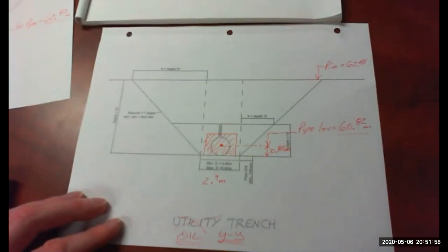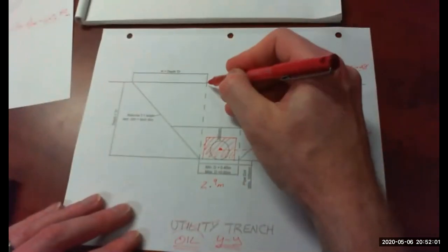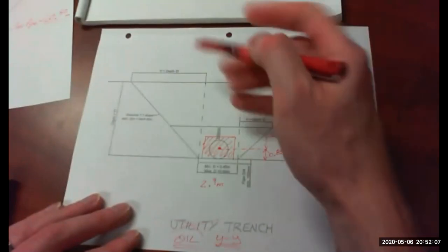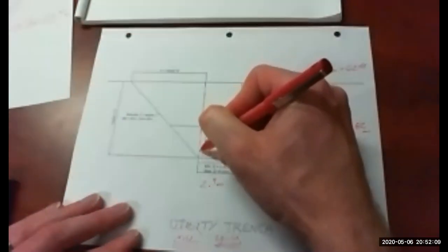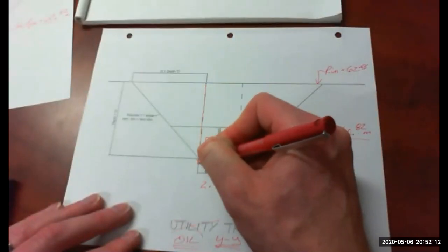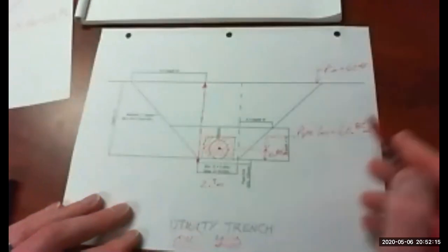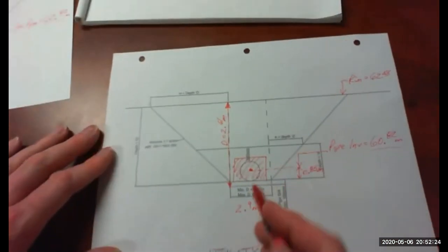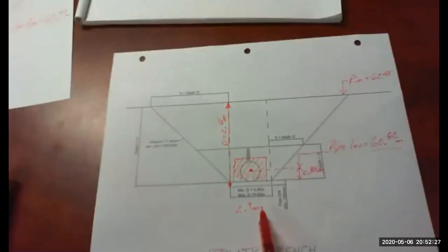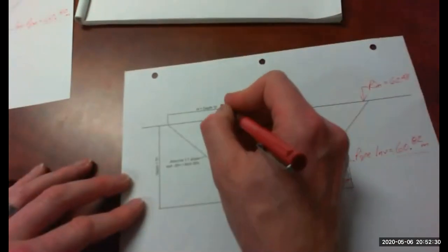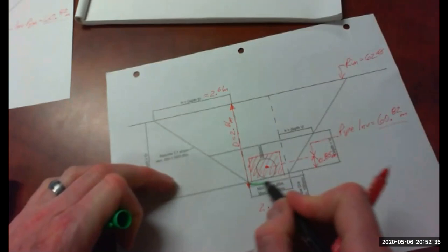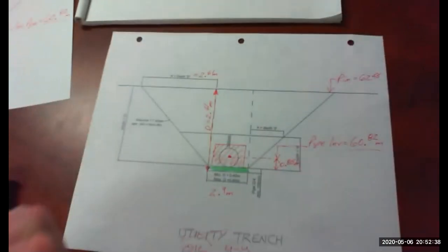Okay, so what this tells us is if the rim, the pipe invert, and this depth don't change, what that tells us is the overall excavation depth doesn't change, right? So we don't need to calculate it, we just need to copy it from our previous cross section. Still 2.61. The difference is the length of the box in this direction. That's the only difference. So again, up here, 2.61 meters. So I'll color in the bedding just for completeness.